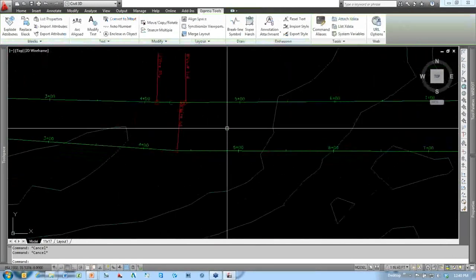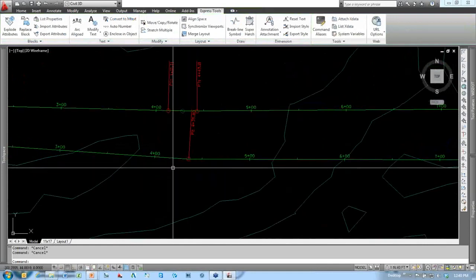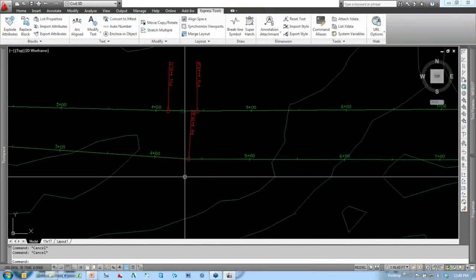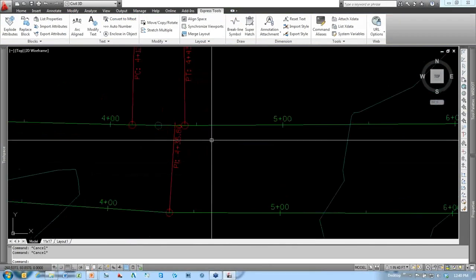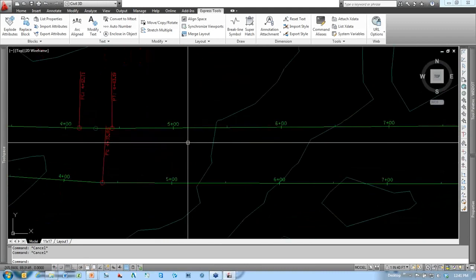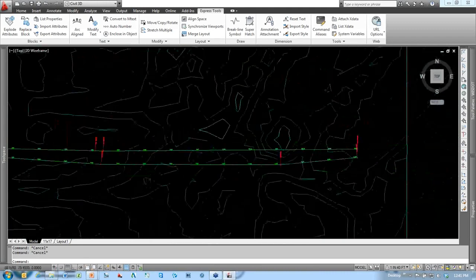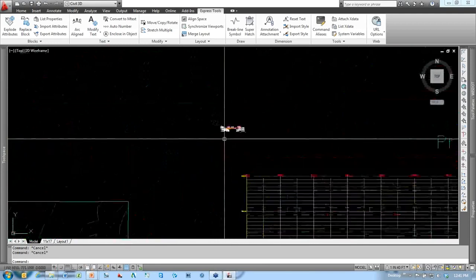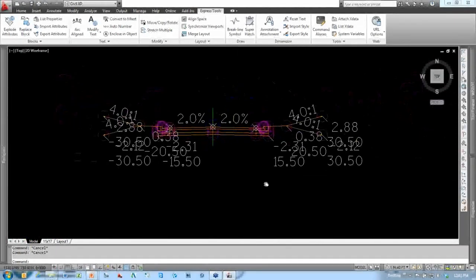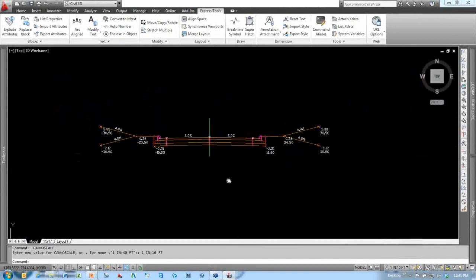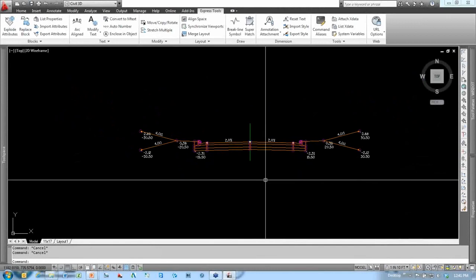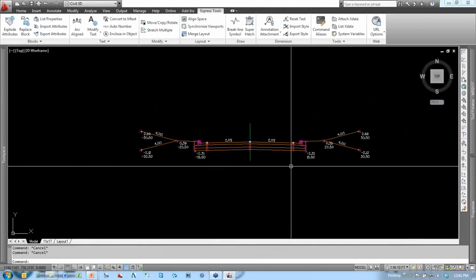Let's look at creating a roadway where it has no curbs on the outside, ditches on the outside there, so there's a shoulder as well. On the inside there's a little rollover median. Let's go ahead and define that. So it starts with our assemblies. If I come over here, here's the assembly we pretty much had in the previous drawing. What we're looking at here is an eastbound and a westbound, and many times you have separate alignments and profiles that define that geometry, and then a median in between